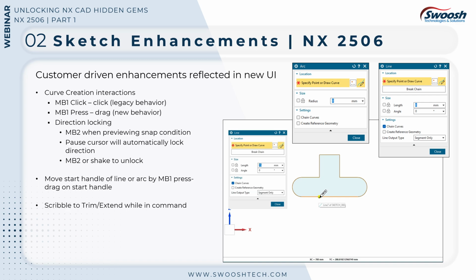So Siemens has introduced several new interaction methods to make curve creation more intuitive and flexible while maintaining support for legacy workflows. The legacy interaction of a two-click method for creating your curves still exists. The traditional method of creating a line remains available inside the sketch solver here. Simply click once to set the starting point, move the cursor to your desired endpoint, and click again to complete the line.